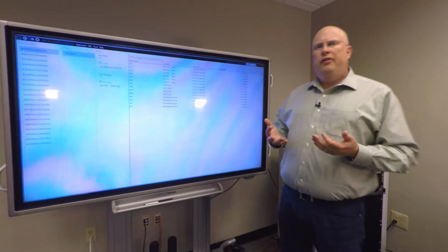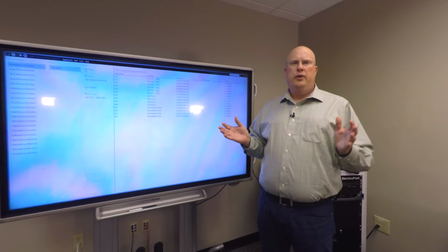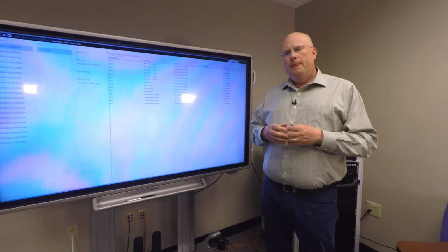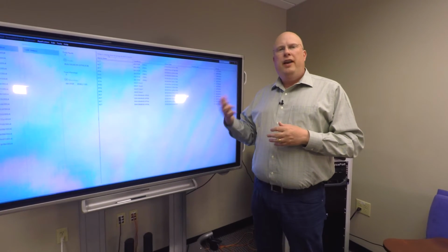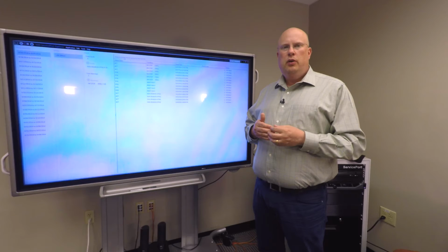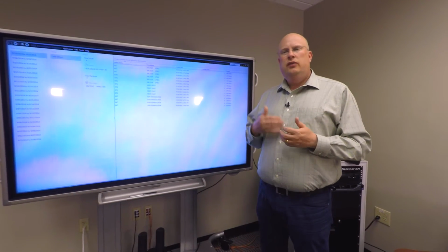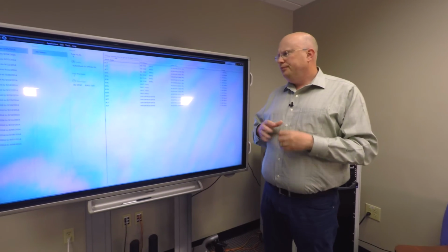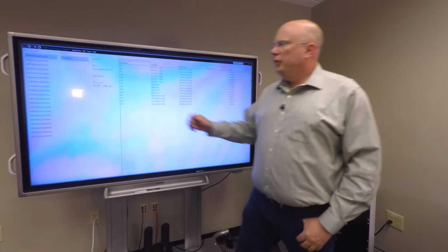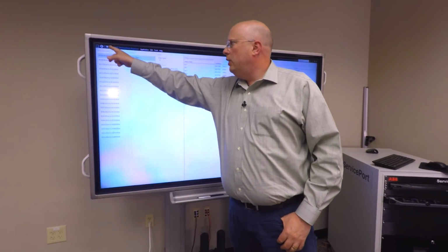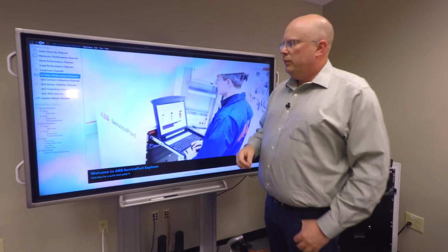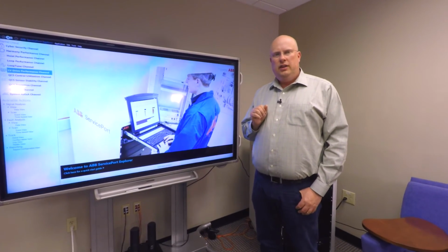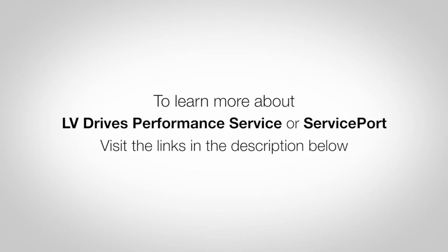And an example of what one can find here, we are monitoring 25 drives. 5 of them are sitting on each breaker circuit, and we noticed that the ones fed by breaker circuit A have more earth faults than the rest of them. That is a really great indication that something is wrong with that group and with that breaker circuit. So it's a powerful addition to the LV Drives channel to see all the faults, and we really think you will like it. So that's really quickly about the LV Drives channel. Thank you very much.